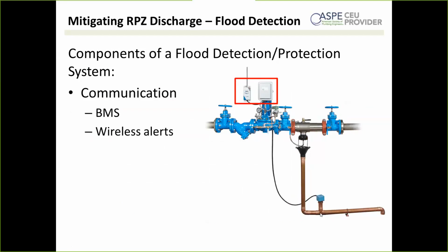I know in this particular one, you could set it to a second, or you could set it to an hour. Maybe if it's outside somewhere and you just want to shut it off because it's going to be wasting water, you might set it for several minutes because maybe the situation will resolve itself. But like I said, if you're in a sensitive area, you have to squeeze a backflow preventer in some place where you're just not going to have adequate drainage with, more than a few gallons of water coming out is going to create a problem for you. You're going to want to make sure that the system is set up in such a way that it's going to activate quickly.